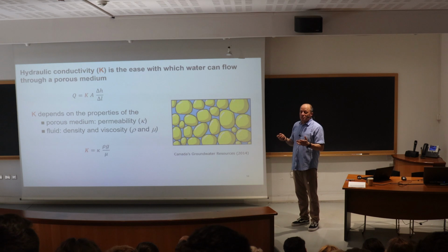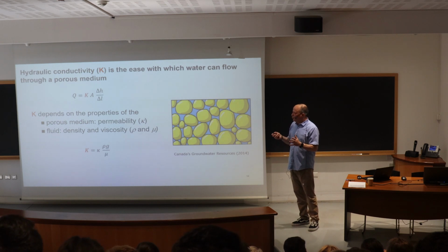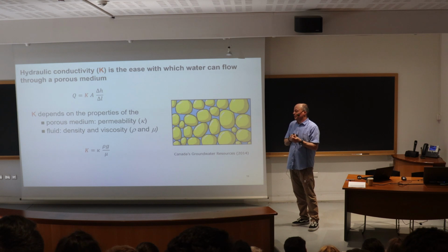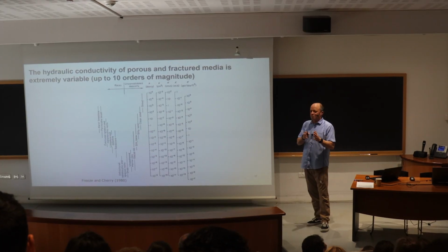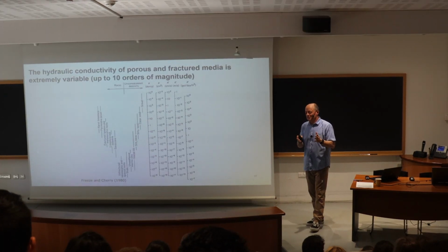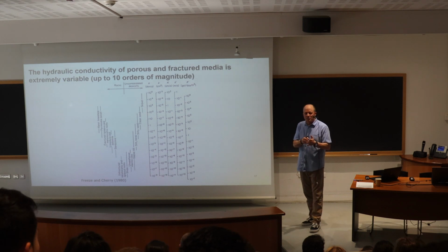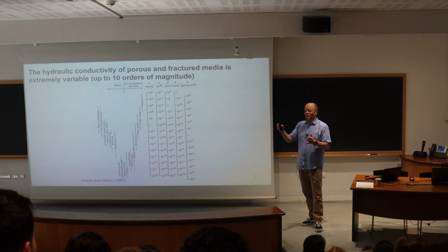But for most applications, we only work with hydraulic conductivity, but if you're interested in multiphase flow, then you basically work with permeability and not hydraulic conductivity, because you have saturation varying between 0 and 1. You will not get 0, it might be some fractions of a percentage, to 1, it's not 13 orders of magnitude.